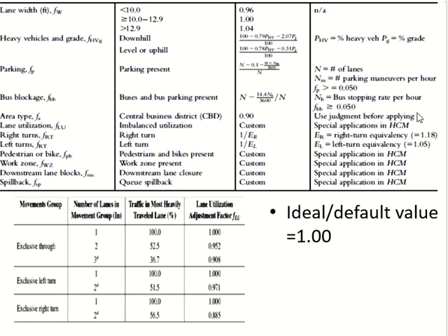How do we calculate the parking adjustment factor? This is the equation. This number is very small, but it is NM. What is NM? Number of parking maneuvers. Parking maneuvers are 2, going in, coming out. So how many in the peak hour, or in the hour when you are doing this? Then the number of lanes, where? In your group, in your lane group. Keep it in mind.